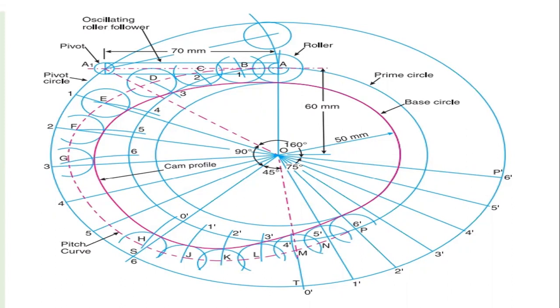Here I am going to conclude this section. So that is the procedure for drawing the oscillating roller follower, which you have seen. We have to take the oscillating distance. By taking this distance, we have to fix this point of the roller, and then we have to move it. So that is by taking the section from here. The oscillation starts from the point in this section.